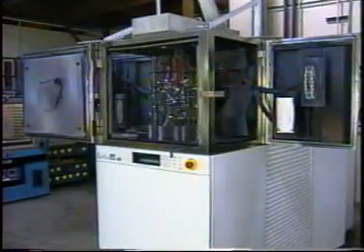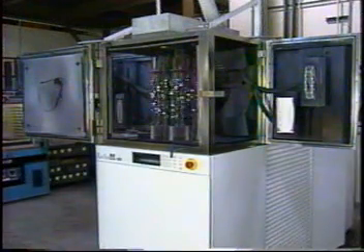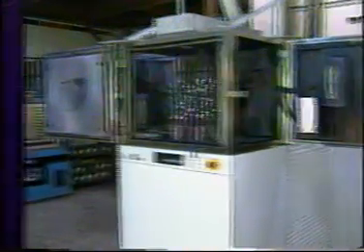At the same time, a reactive gas is fed into the coating chamber to provide the non-metallic component of the hard coating. The ionized metal and gas atoms are then accelerated against the tools by an electrical field. On impact, they are deposited as a thin coating with a desired composition. Because PVD is a line-of-sight process, to ensure uniform coating thickness, tools and rotating fixtures are passed through the ion plasma or cloud created by the arc or argon-bombarded targets.